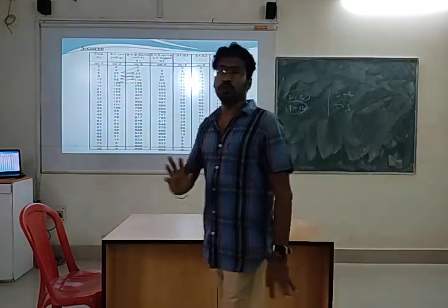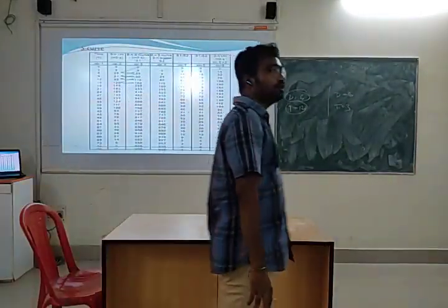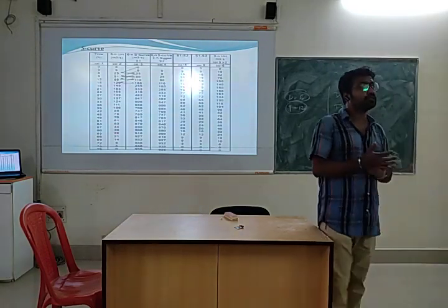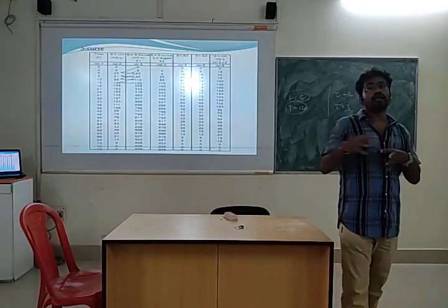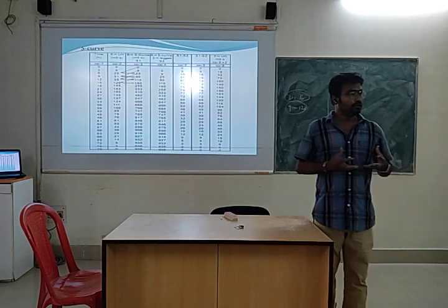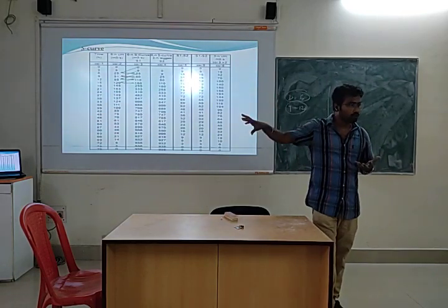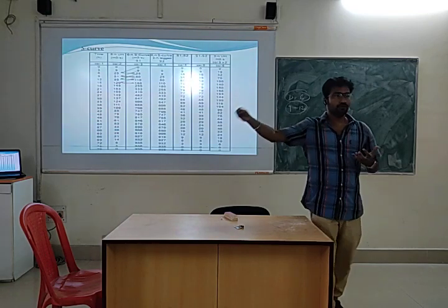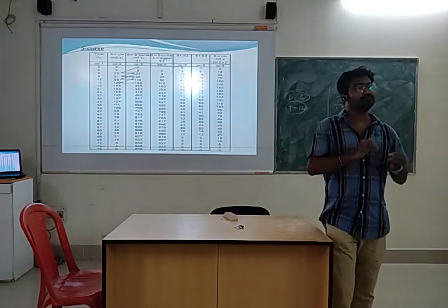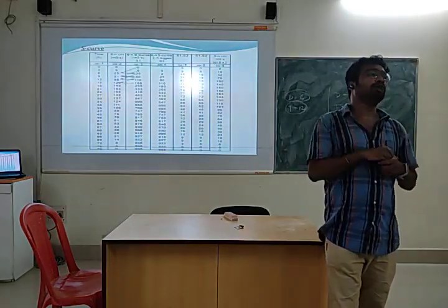Clear? That was up to the hydrograph part, where we have learned about various hydrographs, and we have learned about the unit hydrograph, because finding the hydrograph for each and every storm is very difficult, right? How can we find out the hydrograph? By measuring the stream flow, right? By measuring the stream flow, we can find out the hydrograph. Okay? So for each and every storm, it is difficult to find the hydrograph. That is why, what we do is generally plot one unit hydrograph.